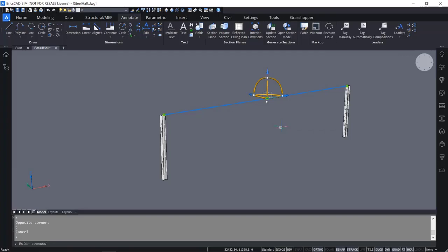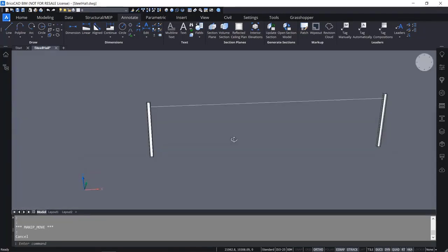We already used that in previous exercises, and now we will use it again quite often to mirror things, to move things. So now we can choose the down axis, so the one pointing up, and we move our line 400 downwards. So type in 400 in the input field, and then you see it's 400 down.